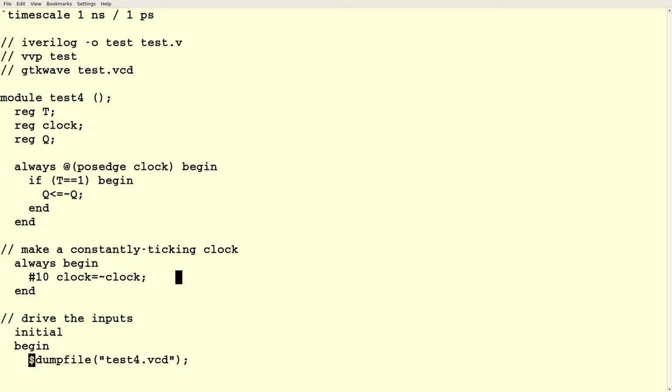At some point in time I want to be able to say set this variable equal to 7. If you're going to do that, that variable's got to be a reg. If you say I want this variable to have whatever value is coming out of this circuit, that can be a wire. It could also be a reg. But it really just needs to be a wire because we're going to take the output of this circuit and connect it to this variable. So it's really just the end of a wire.